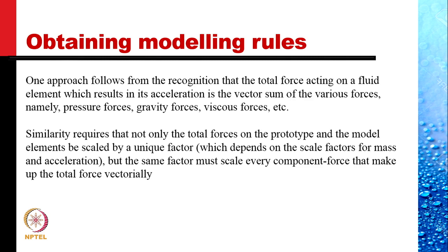Similarity requires that not only the total forces on the prototype and the model elements be scaled by a unique scale factor, which depends on the scale factors for mass and acceleration, but the same factor must scale every component force that make up the total force vectorially. So it is not just the inertial force, but the viscous force, the pressure force, and the gravity force. They also must be scaled by the same scale factor Kf.